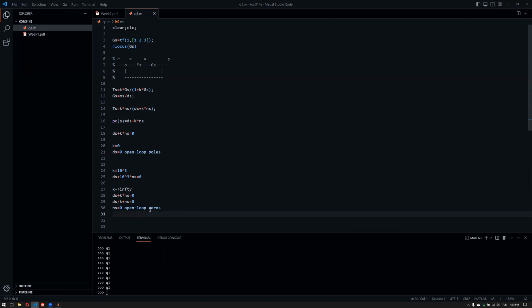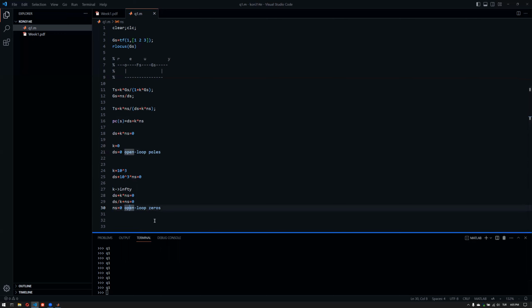So therefore, when we are plotting a Root-locus plot, which, by the way, can be a positive Root-locus plot or a negative Root-locus plot, depending upon the sign of the gain that you're trying to come up with. In our case, we are looking at the positive one because we are looking for positive gains. We start with the open loop poles, and we end up in open loop zeros. Now, for such a system, you have 2 poles, but no zeros. Well, actually, you have zeros, but they're not finite zeros. We call these poles finite poles, and these are infinite zeros because there should be zeros.